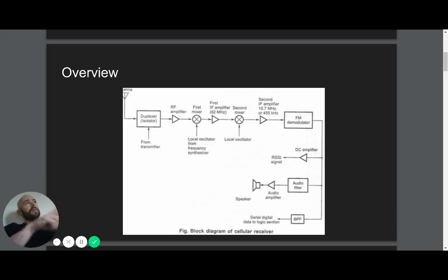And in our case, since we're demodulating it, we're multiplying it against another carrier frequency, which is shifting, giving us multiple copies. And one of those copies is going to be back at the frequency that we're looking for. So this is going into the demodulator, which is then fed into the digital analog converter, which is then used to do various things, whether that's voice going to the microphone, or that's a text message getting sent to your screen, etc.